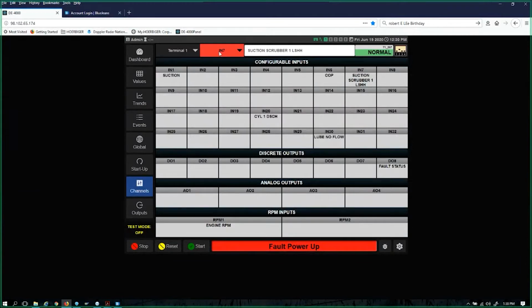Right. Well, I think if we've been in this business long enough, we've all seen suction scrubbers that get filled up with foam that happens to have just the right buoyancy to float the float. So you're getting shut down because of foam, not true liquid levels. So yes, it has its advantage. Now, that subject matter may change, but based on my interviews with the software development team and what I've seen and tested so far in the field, that is correct. Okay, thanks. Yes, sir. Thanks for the question.